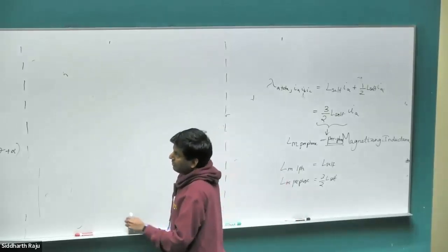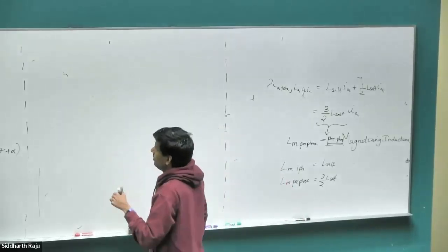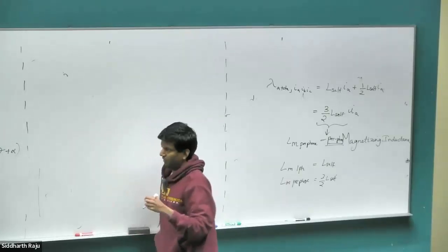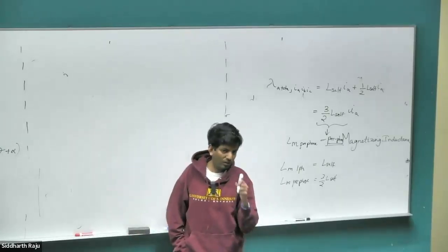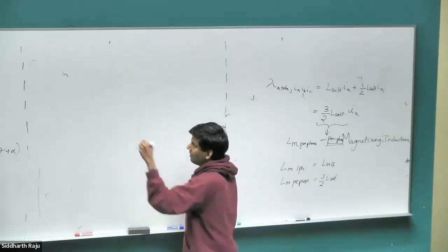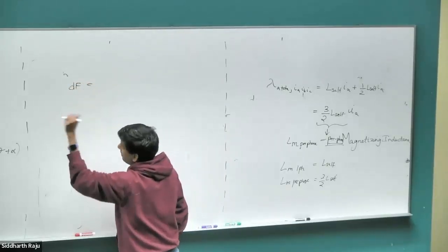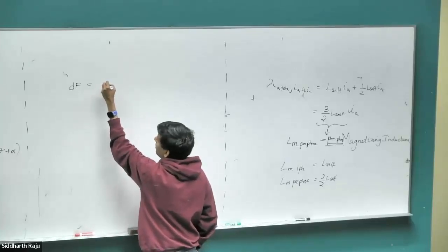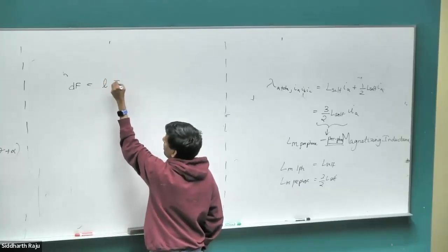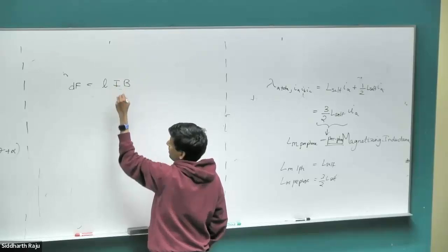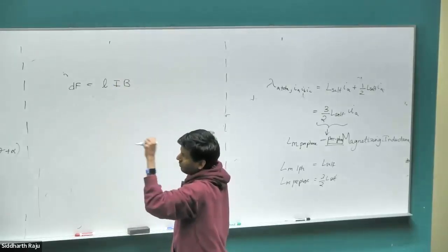okay, so now this magnetic field that we have is going to interact with the conductors in the stator, which is carrying current, to create a force on the conductor. Right? And we have an expression for that. So the differential force created on the tiny set of conductors is going to be L times I cross B, where I is the current going into the whole set of conductors.